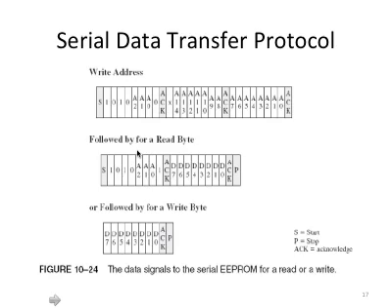We conceptually represent these control signals as start, acknowledgement, and then here stop. You don't have to know exactly how these special control signals are implemented at the circuit level, but just know that we do have these special control signals in order for this protocol to work.